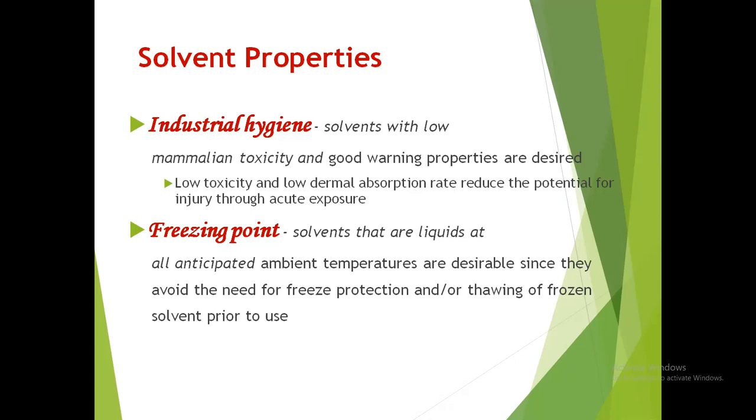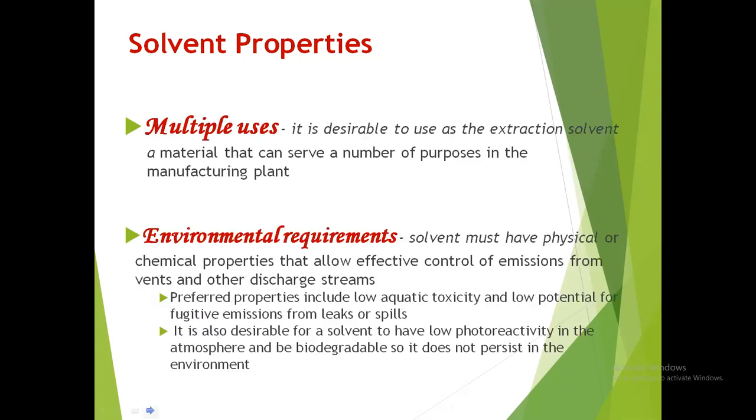Now, as to freezing point, this is a concern for those in the western part of the globe when they have winter. So solvents that are liquids at all anticipated ambient temperatures are desirable, meaning they should not get frozen easily, since this avoids the need for freeze protection or thawing of frozen solvent prior to use. Because if they get frozen easily, then there's a need for thawing prior to using it.